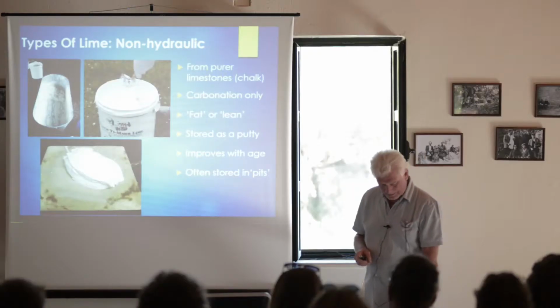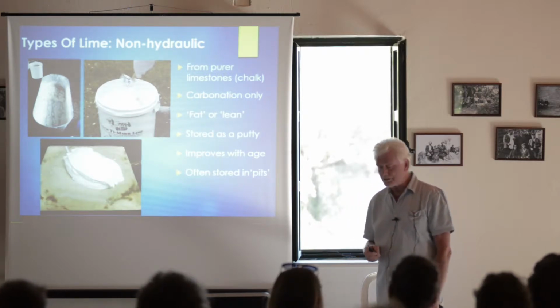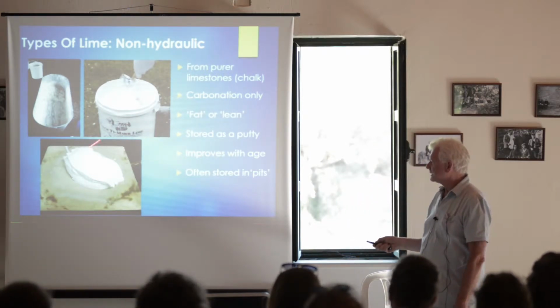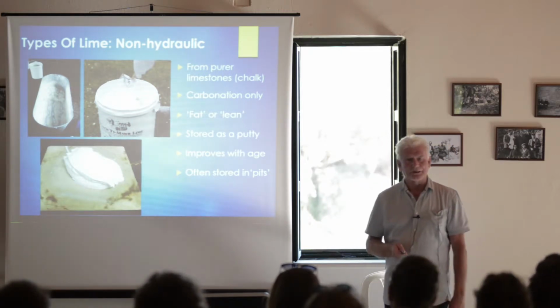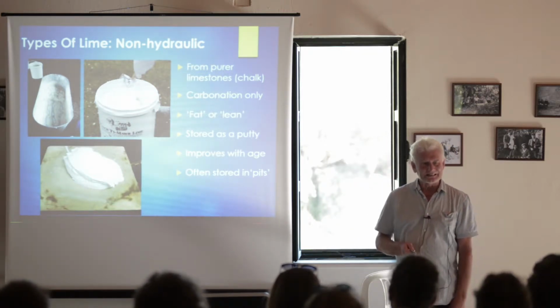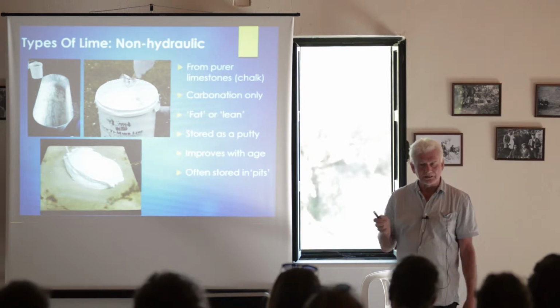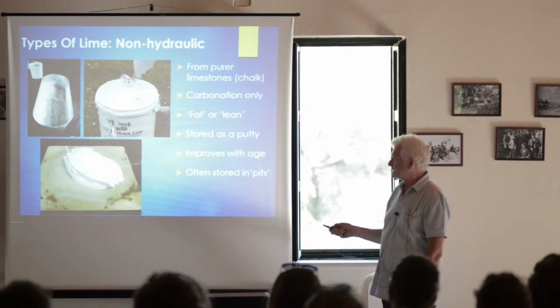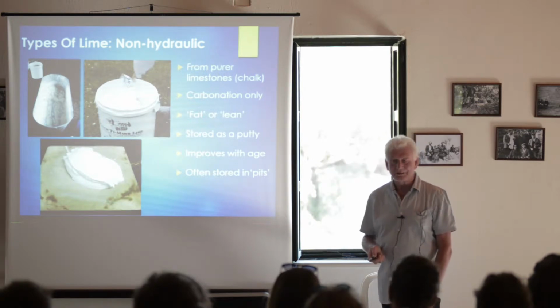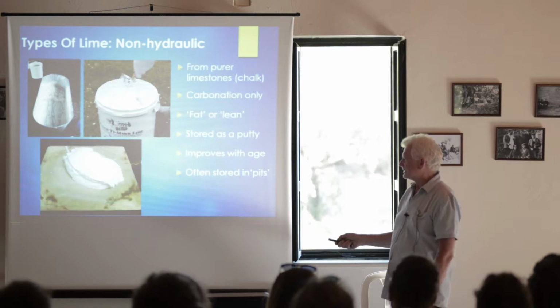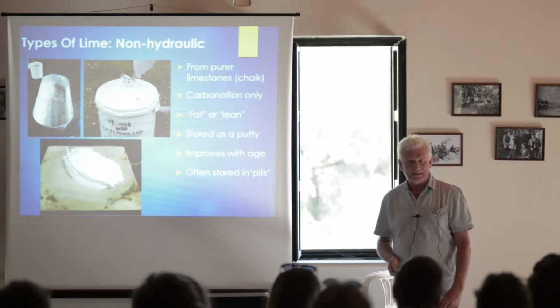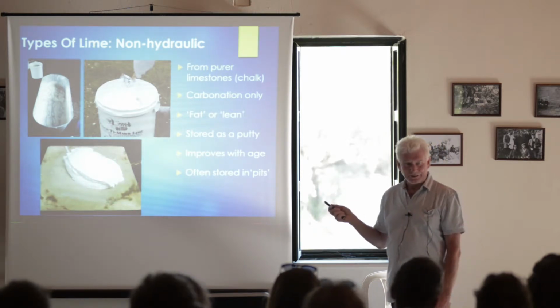They say that you shouldn't use lime putty if it's less than 1 year old. In reality, that doesn't happen because a lot of these putties are now produced commercially, and they're delivered to site in bags, or in a bucket like this, and they're often no more than 3 months old.